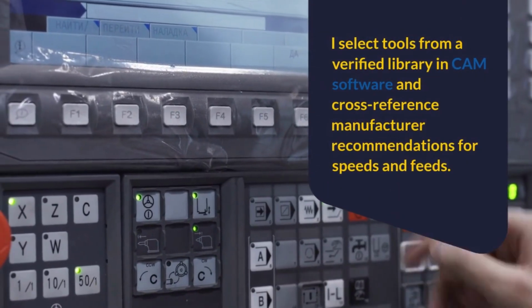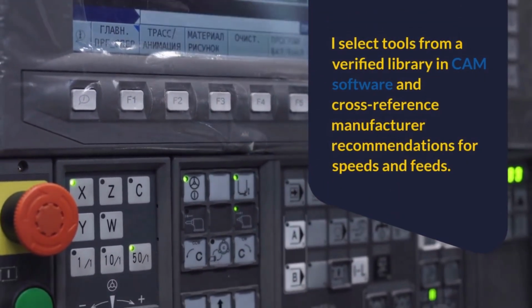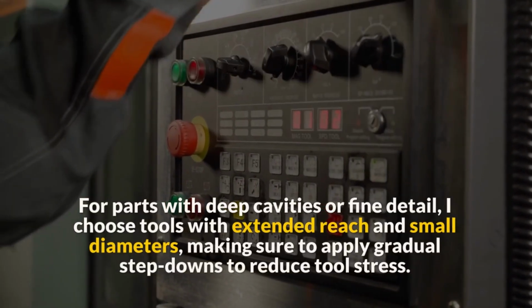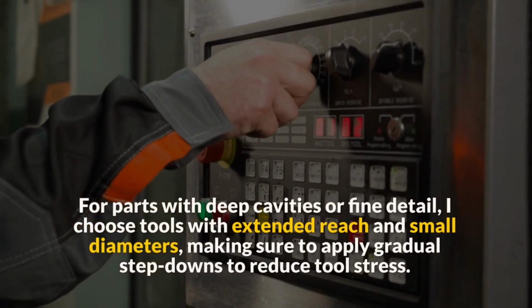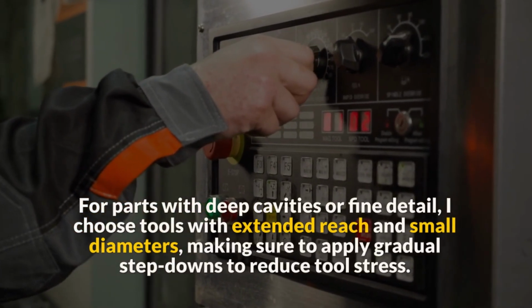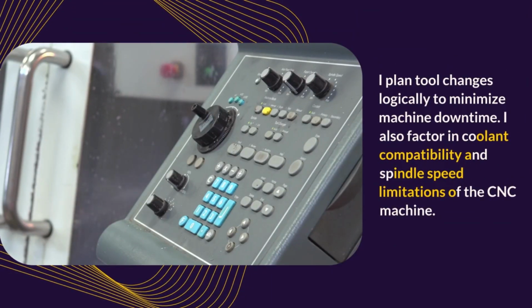I select tools from a verified library in CAM software and cross-reference manufacturer recommendations for speeds and feeds. For parts with deep cavities or fine detail, I choose tools with extended reach and small diameters, making sure to apply gradual step-downs to reduce tool stress. I plan tool changes logically to minimize machine downtime. I also factor in coolant compatibility and spindle speed limitations of the CNC machine.